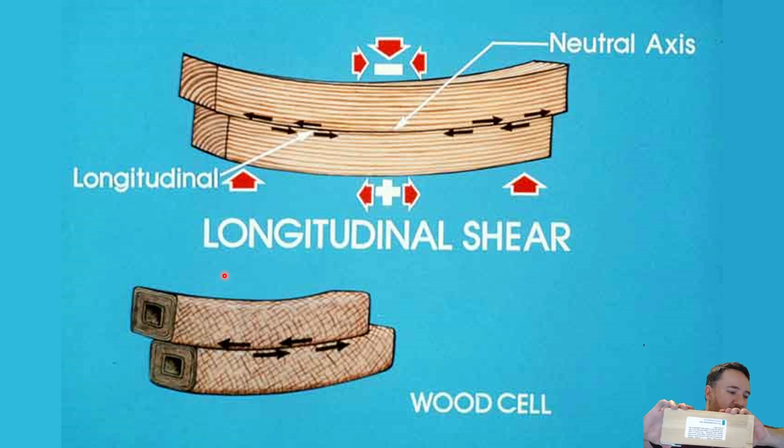So if I'm bending this, I have some shear, and that shear is highest at the center of this rectangular cross section. And at that section, basically what's happening is that the fibers are trying to slide against each other, just like shown in this figure at the top. So one set of fibers wants to go one way, the other set of the fibers wants to go the other way. We're shearing it like this.